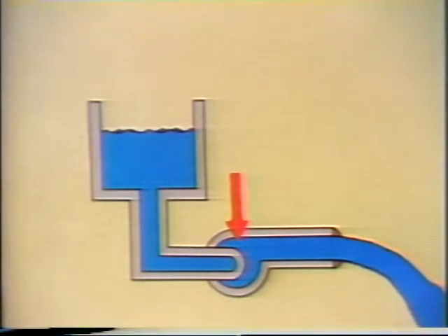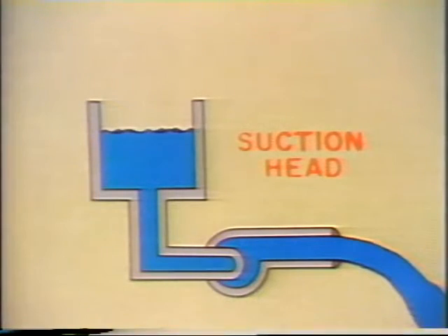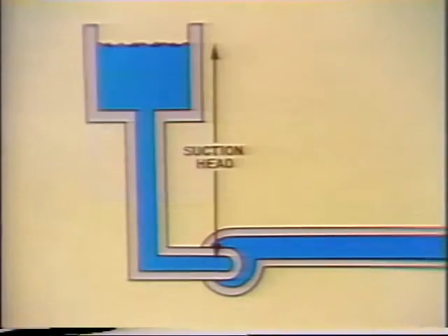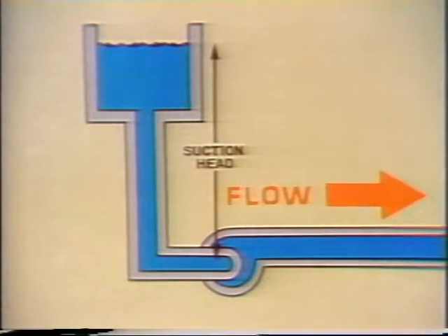Now, this pressure, called the suction head, can be provided by a tank. When suction head increases, flow also increases. This tells us that head has a positive effect on the flow rate of fluids. But at all times, a minimum amount of suction head must be available at the pump suction. If suction head decreases below the minimum value, problems occur, and the pump may be damaged.